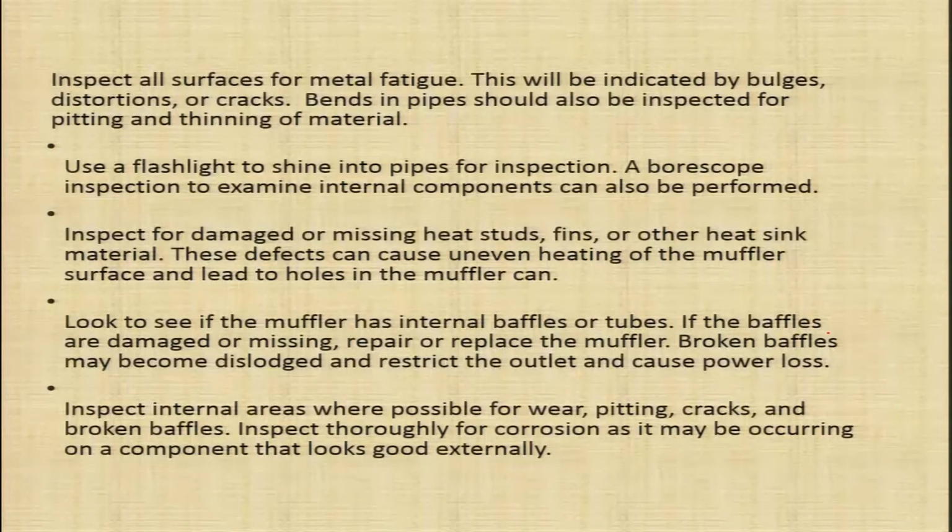So, the internal portion of the exhaust system should also be carefully inspected to see if there is any wear, any pitting, any cracks or any broken baffles. So, the internal areas should also be carefully inspected apart from the external area.